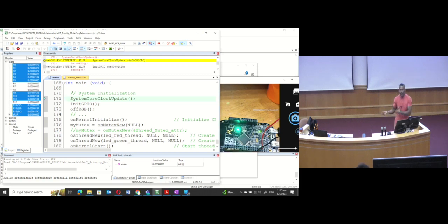Now when I delay, what happened? I transition back to red, correct? But in red, what am I doing? I have already finished one iteration of the loop. I already released the mutex and now I'm going back to acquire one more time, correct? And when I try to acquire one more time, what happened? I will try to lock, but I cannot lock, which means now I will go to a block state.